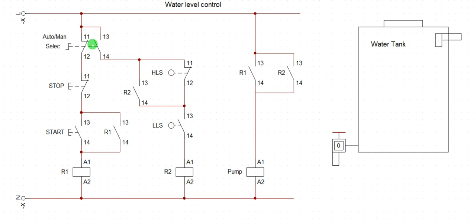This is my selector switch to select which operation is going to be activated. At present it is on manual because this is closed. This selector switch is on manual mode. If you want to put it on auto mode, you operate it, and it will open this contact and close this contact. At every given time, the selector switch must close one and open the other of the two contacts here. Then this is the stop button and this is the start button.